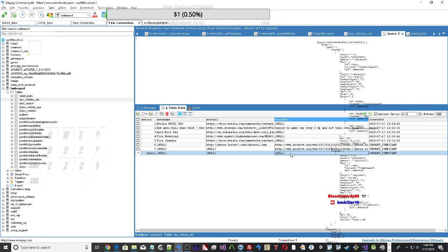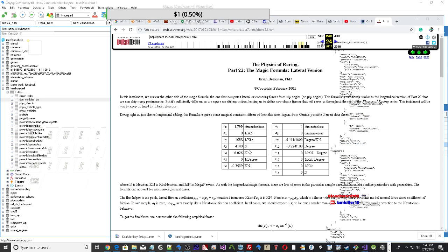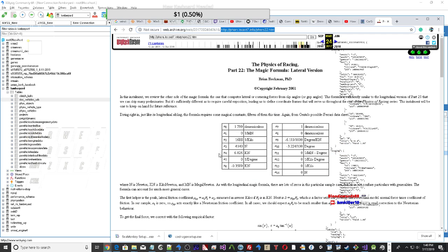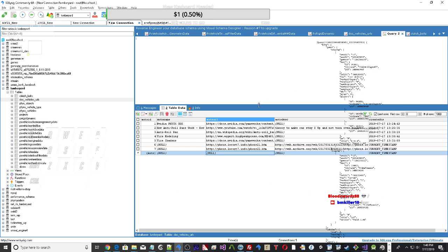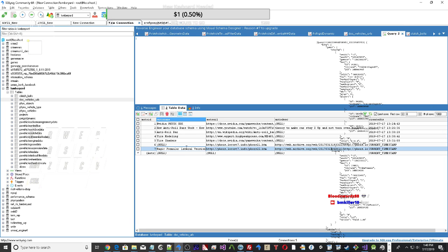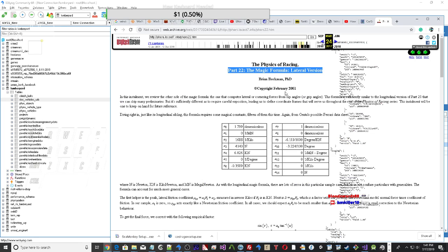Details of many of the parameters and functions above can be found in section Tuning Guide. The function setupNonDrivableSurface, which sets up scene query filter data for each suspension raycast, shall be discussed in more detail in section Filtering. Further, the link between tire type and tire friction shall be made clear in section Tire friction on drivable surfaces. Finally, the use of the function setWheelShapeMapping shall be clarified in section Wheel pose.